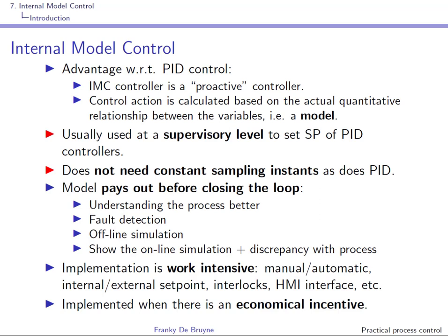Well, if you have to implement this internal model controller yourself in a PLC, this is going to be work intensive, and you're going to do it only if there is an economical incentive. Remember that if you implement a control algorithm yourself, you're going to have to implement all modes: manual, automatic, internal, external, interlocks, a human machine interface, and so on.